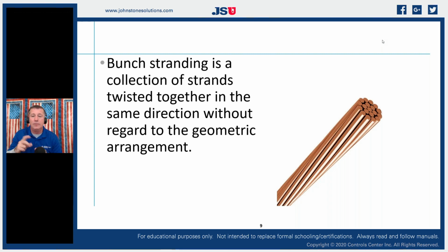It's just a natural motion of our hands. But you'll find that there are wires that twist well in one direction, but don't twist well in the other direction. That's because of the direction in which they are constructed as they're being wound. So that direction will play a factor in the correct way to twist those wire nuts.